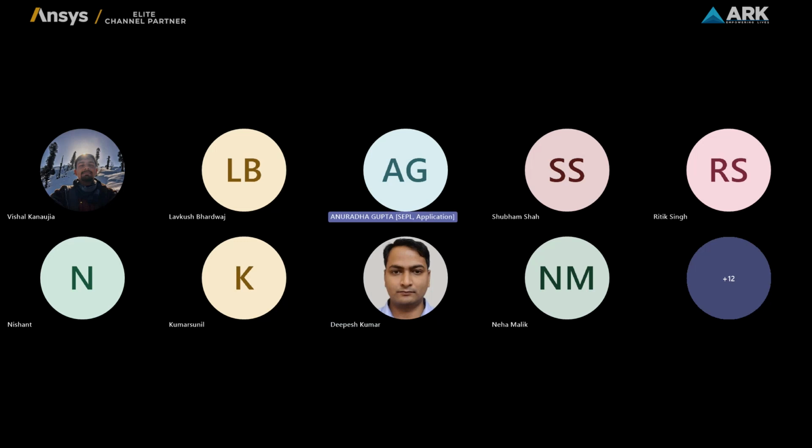Okay, so in radiated immunity, is there a complete range of 20 megahertz to 2 gigahertz or 4 gigahertz? It is there. Actually, I'll answer this question. The tool is not limiting you to any frequency limit. You can do it for a wide range of frequencies. The only thing is, whatever workflow I have shown you is for conducted and radiated emissions. Radiated immunity and conducted immunity both have different workflows.